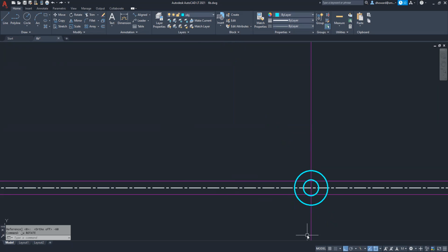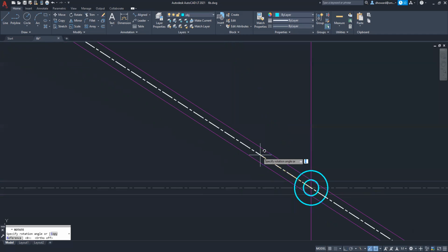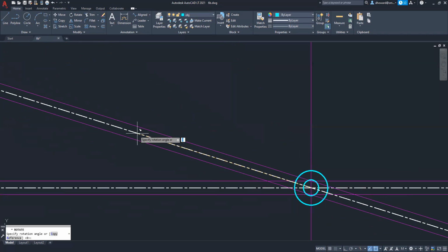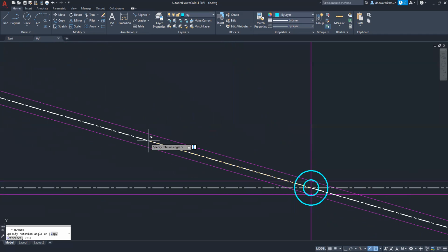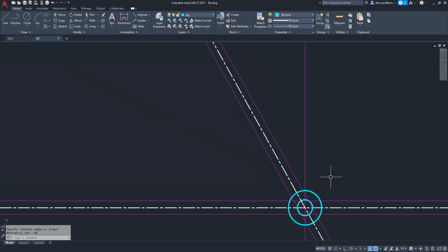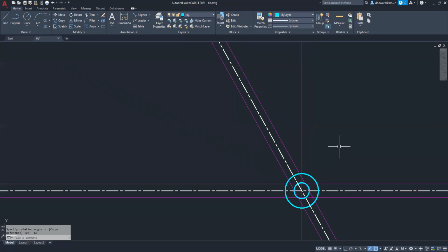And that's what I want to do. I want to leave a copy behind. And I know that's an option. You can see over here it says copy. Maybe I just click on it and then type in the -60. There you go. Just click the copy. I typed C and then enter, and that usually works. I'm not sure, but anyway, just clicking on it worked.